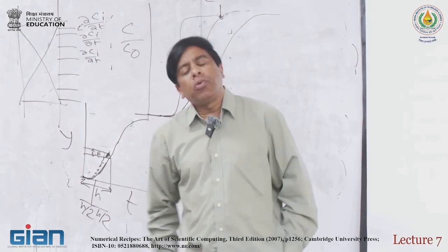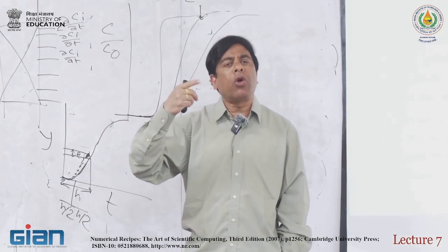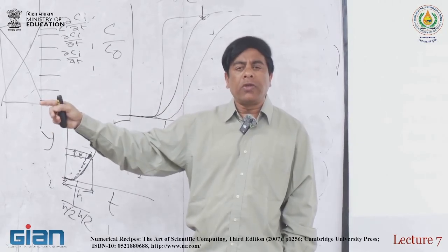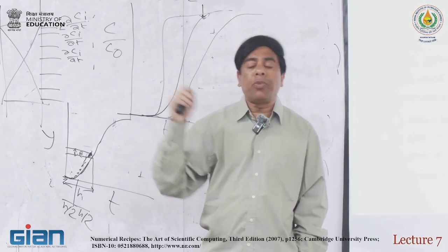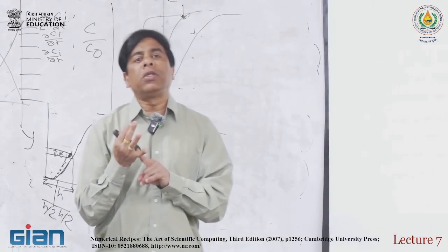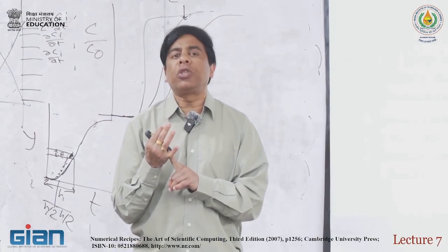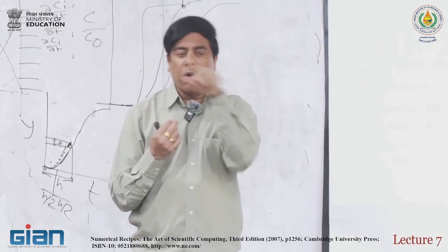The way you have to see it, and I will talk more about it, is how these tolerances are actually defined. There are a bunch of tolerances in Aspen. For equation solvers, we have many tolerances. One is the relative change in the variables: when I am taking a Newton step, I'm basically looking at x(k+1) minus x(k) over x(k).